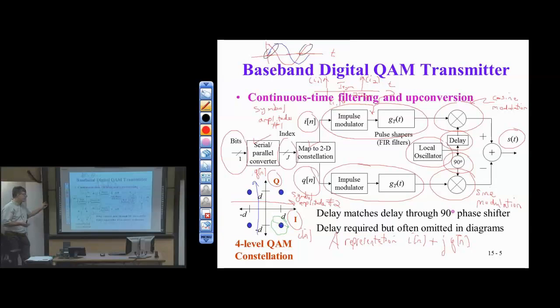Now, once it goes through a channel, there's a little bit of cross-contamination or leakage, and you saw and quantified that in homework 3. But now, if we look at this constellation map, we'll see that the phase starts to matter more. Here, the phase error can still be maybe 45 degrees, and I'm doing a pretty good job, and 90 would get me in trouble pretty fast.